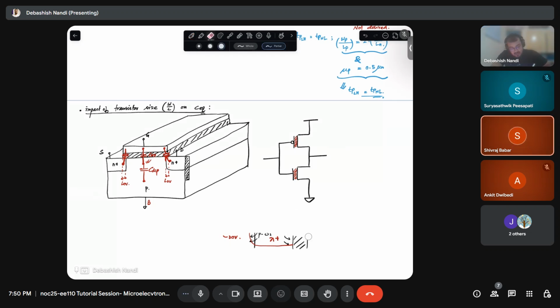I have one question. Is the shallow trench isolation oxide and the gate oxide the same material or a different material? The material is the same, silicon dioxide, but the processes through which the oxidation is done are different. Basically, oxide is grown by oxidizing your silicon. The gate oxide is at the heart of your device, the main thing that is controlling the field effect of the device.